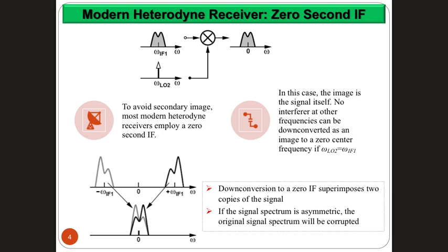And with the advancement of the technology, things that have not been doable within the chip, and you had to take those components outside the chip because of size, because they need larger size, so they cannot fit inside the chip, or they need some passive components that cannot be implemented within the constraints of the chip, or they suffer from high undesired effects such as high nonlinearities or high interference effect on other modules and so on, as we will see when we talk about the other architecture of the transceiver. Then you have to take them outside chip so that they do not affect the other components, right? So there are many reasons for this.